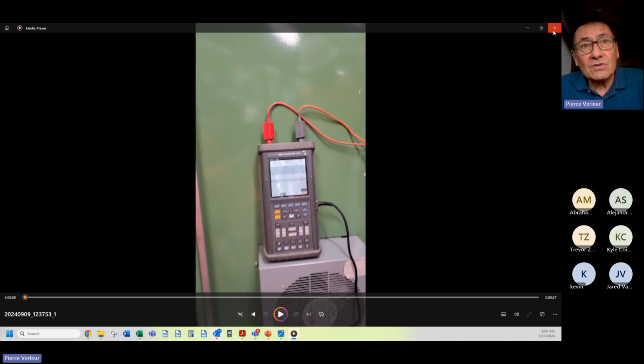And now I realize I can use a fiber optic link on long encoder lead lengths and still maintain the ability to commutate, where the timing of the pulse is extremely important, because I've got the pulse timing coming from the encoder all the way over the lead lengths back to the VFD. The VFD processes it, then starts changing its PWM output according to the encoder feedback. That loop cannot be a long period of time. That's got to be measured in small numbers of milliseconds. And the fiber optic link did a great job.